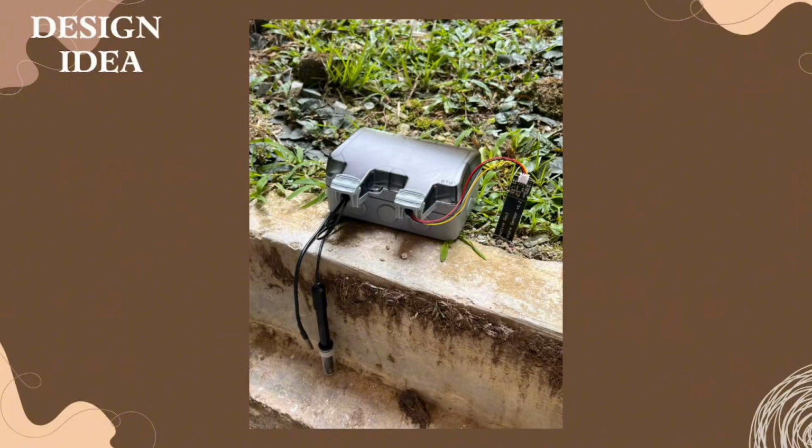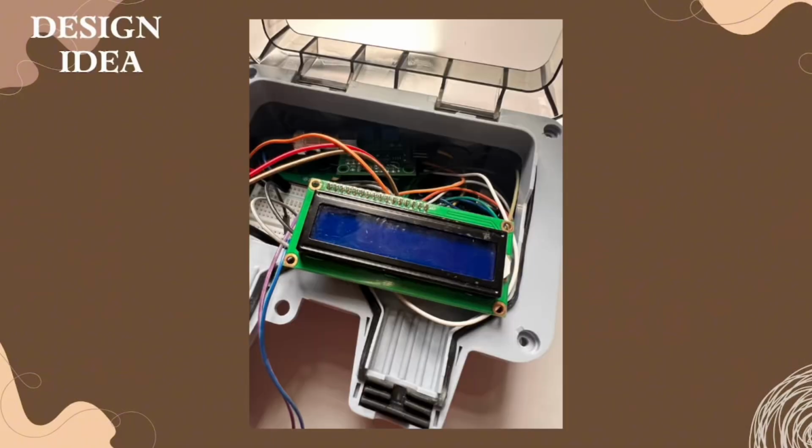So here, you can see the complete device. At the heart of it is a rugged, waterproof and weatherproof casing. This was essential based on the user needs, since we are deploying this in harsh outdoor conditions, especially near palm oil plantation stream water. On the front, we have integrated an I2C LCD screen that displays all three key environmental parameters in real time: pH, temperature, and soil moisture.